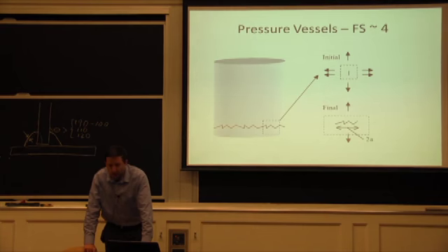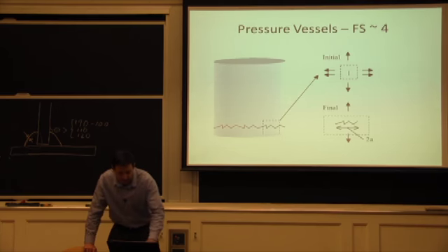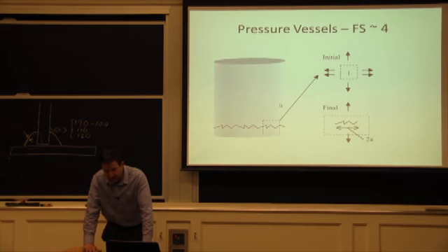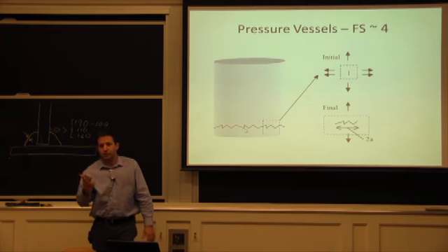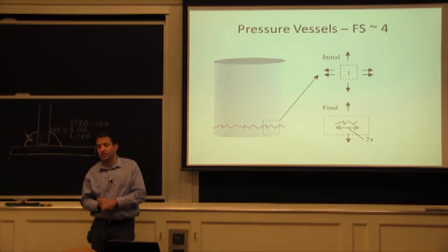You can hide a welded connection that may not be as corrosion resistant as the cylinder itself. And it's the region where you have the most hydrostatic pressure, just from gravity. So they had an overpressure, and they found at the very end that the crack was unzipping around the circumference, which in principle is the direction where you only have half the stress.